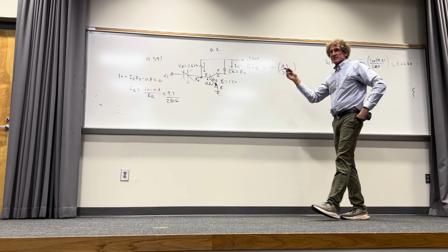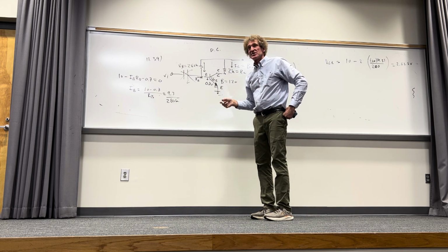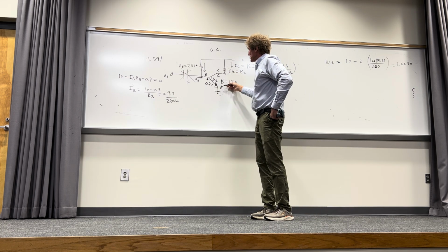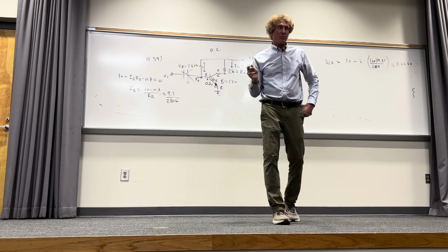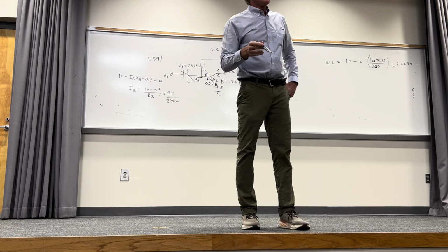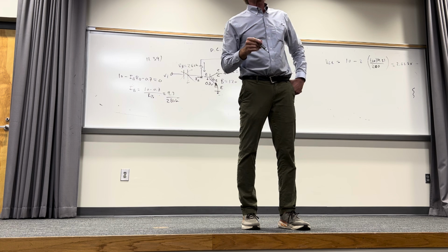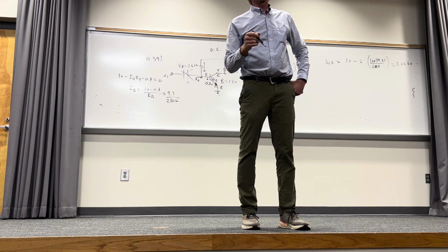The only time the transistor goes into what's called saturation is when the voltage between the collector and emitter is roughly 0.2 or 0.3 volts. Varun, do you remember if they're using 0.2 or 0.3 for actual saturation? I think close to 0.2.